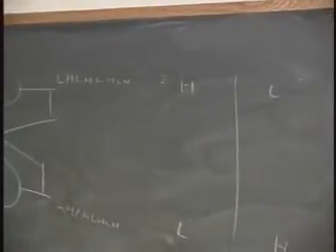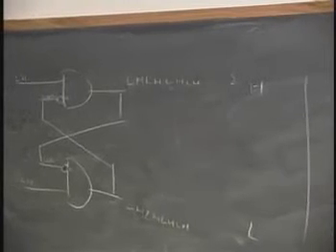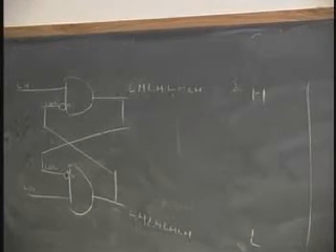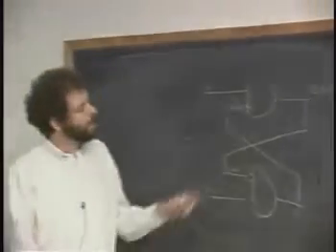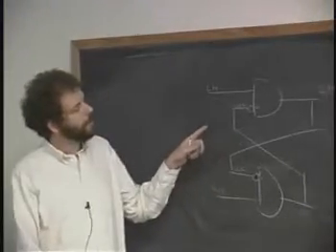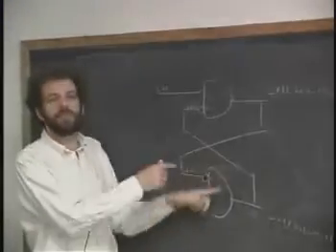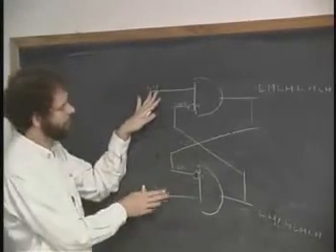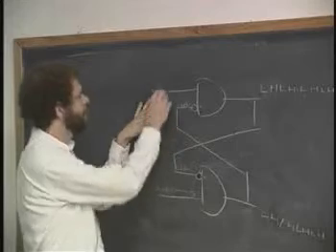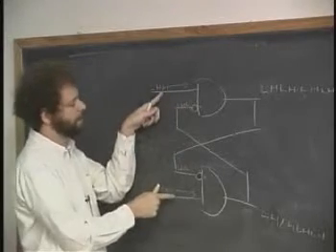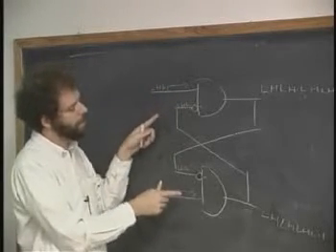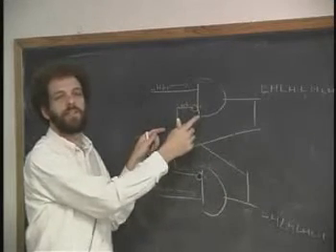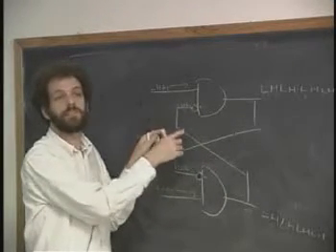Why would that ever happen in a circuit like this? The electricity going around in one path may be a little bit slower than the other. It may be the case that the time delays in the circuit are not exactly the same. Think about this: if both of these are high, and staying high for the rest of time after we press the button at the same time, it may be that the high values as they propagate around are a little bit slower or faster than the lows that are propagating around.